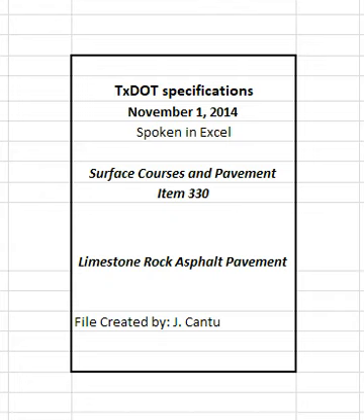4.1.3 Placement and Compaction. For placement and compaction, include proposed arrangements for any required pre-paving meetings, including dates and locations. Type and application method for release agents in the paver and unrollers, shovels, lutes, and other utensils. Procedures for the transfer of mixture into the paver while avoiding segregation and preventing material spillage.